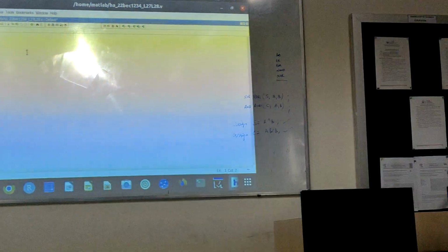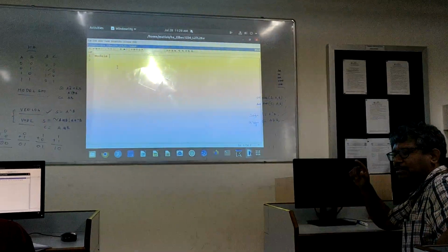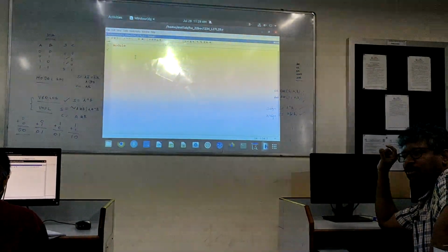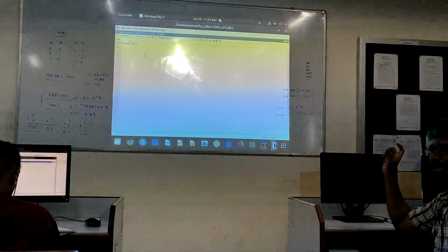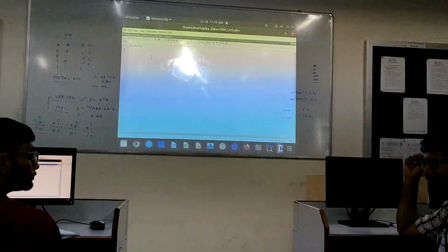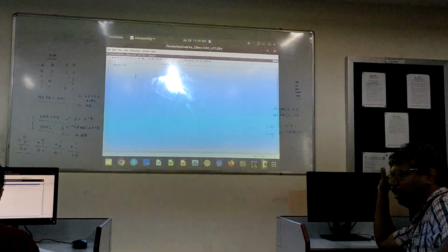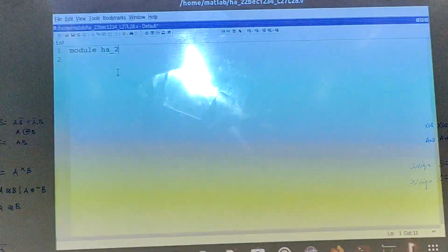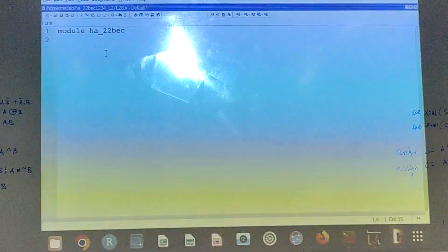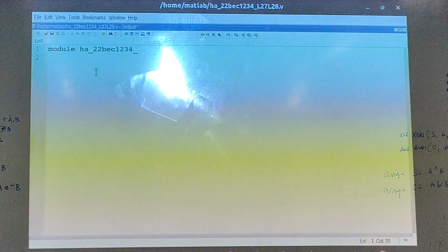So the program syntax will start with module. It is given in the quick reference, you can refer. First explanation, module. In your C language, how do you call the main program? We write main. Any program starts with the keyword main. Here, any program will start with the keyword module. And then we have to provide the module name. File name and module name, please provide the same. It's not mandatory, but if you provide the same, it will be helpful for executing the correct file.